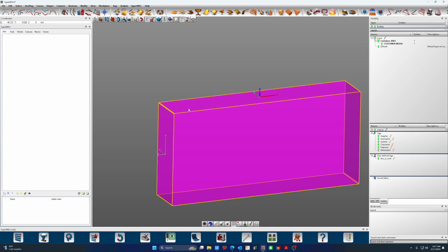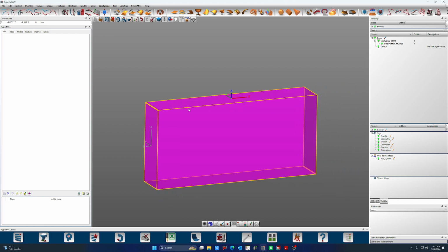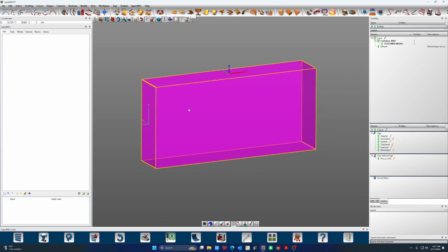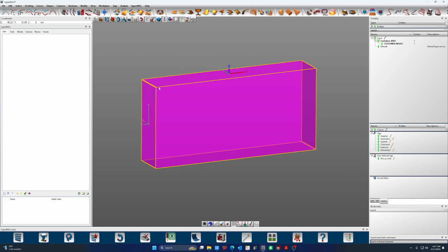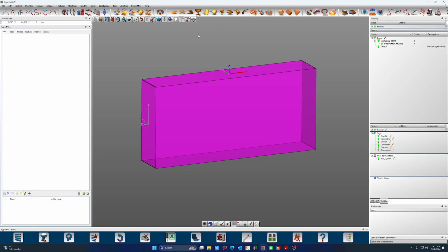The toolpath is a little bit more of a sensitive subject, because some of the stuff you're seeing is just visual artifacts and how well the toolpath is rendered. In some cases, it actually is getting you in a little bit of trouble, and experience will really help you weed that out. There's not a real cut and dry line in the sand there. And lastly, we have a face tessellation setting. It's just a slider for how nicely our model is tessellated.